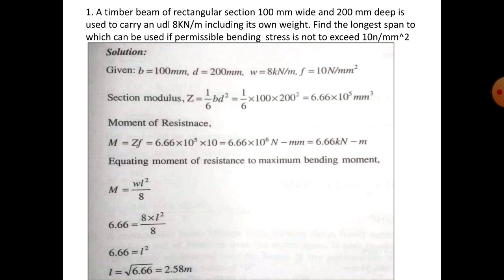Okay, so what it is saying here is that the length and breadth, that is your cross-sectional values, are given, the load is given, and they are given the bending stresses. So you have to first calculate the section modulus. The first thing you have to find out in any problem is the section modulus.